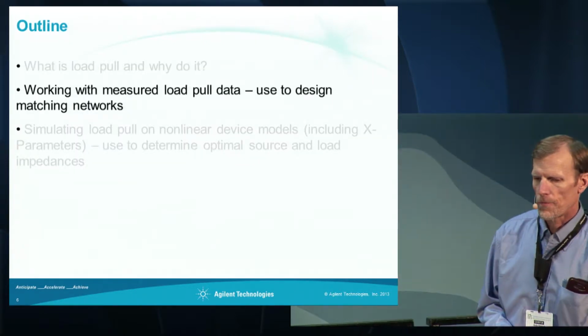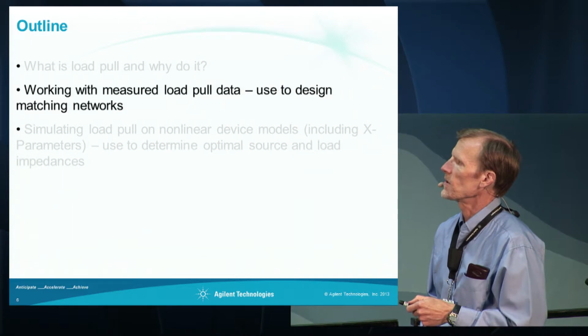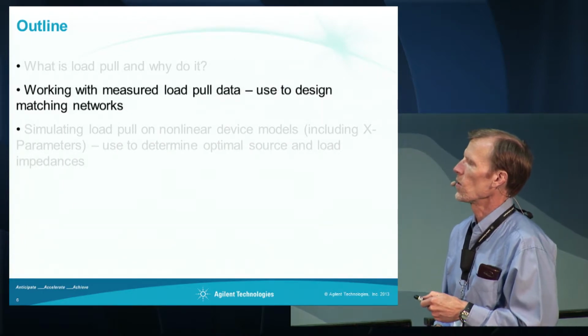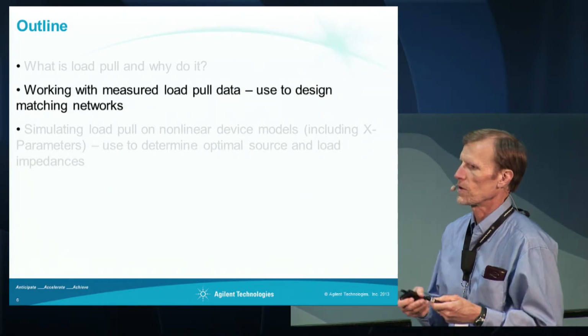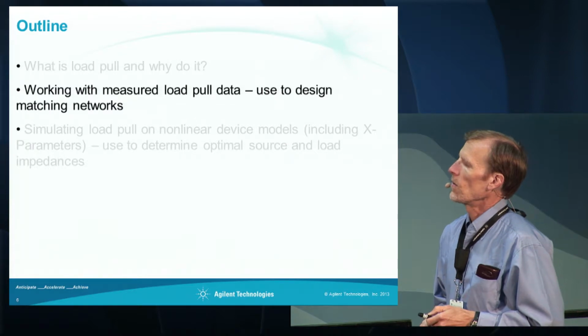Okay, there are two main ways of running load pull simulations or dealing with nonlinear devices. I would say that in one case you have only measured load pull data for the device that you're using, and in the other case maybe you have a nonlinear device model. Okay, the first section I will talk about is where you just have measured load pull data.